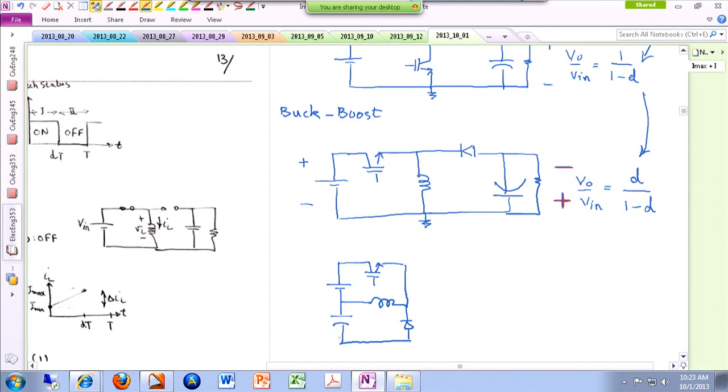To basically point out that using the Buck-boost topology, we can actually transfer energy between elements that are placed in series with each other. And what is the application for that? For instance, you have a string of batteries. Okay?